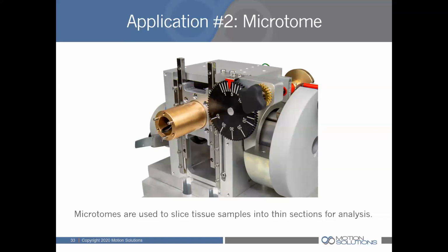What affects that is the rigidity with which the sample is held. So really the most important thing in this application was that we make the strongest, most rigid support for the sample that we could. So you can see we started by using a very, very rigid machined part supporting cross roller stroke bearings. That allows us to control the preload, and being that these are rollers, they have higher stiffness. So that's how we supported the load in the z-axis.